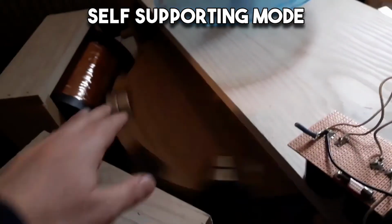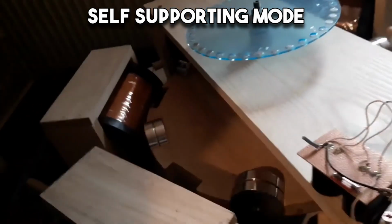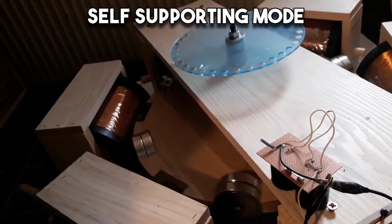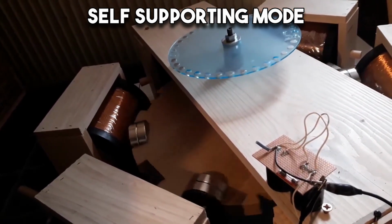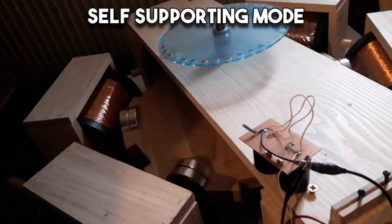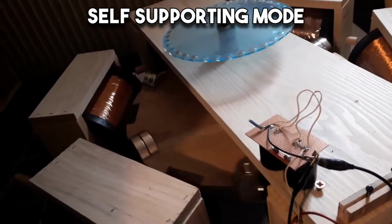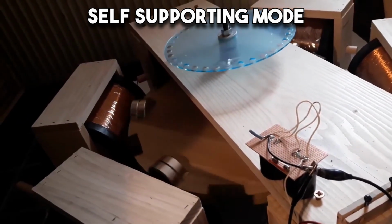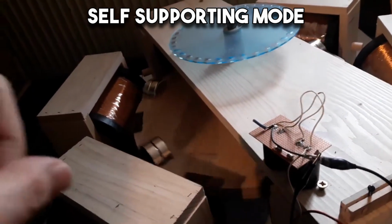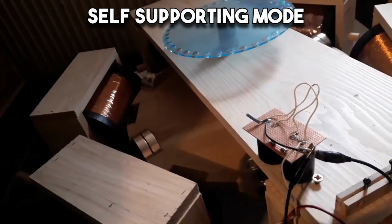Now I will stop the rotor and have a look. Now it's a motor. See? Now I will speed up by the time, because I stopped it from the neutral position. So it's faster and faster. So it's very important that like a generator and like a motor, they rotate in the same direction.